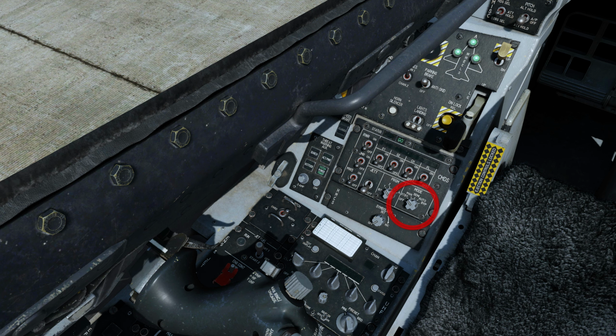In the bypass position, 1 chaff and 1 flare are released with each CMS up command. Note that bypass is a manual mode and that no semi or auto functions are available. With the ECM switch in the operational position, the Go status indicator should illuminate, indicating that all systems are ready to be deployed.